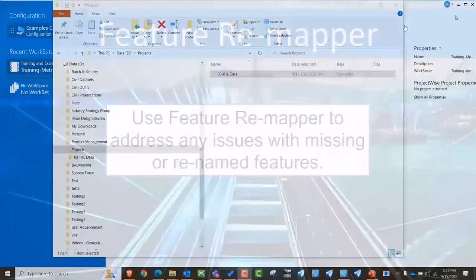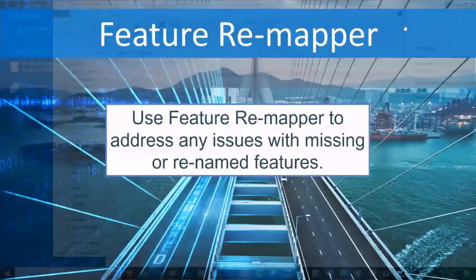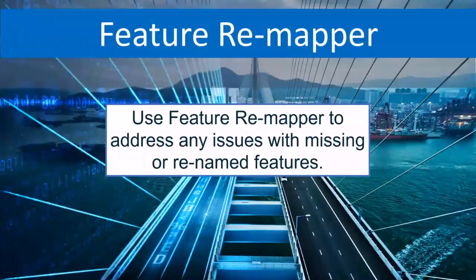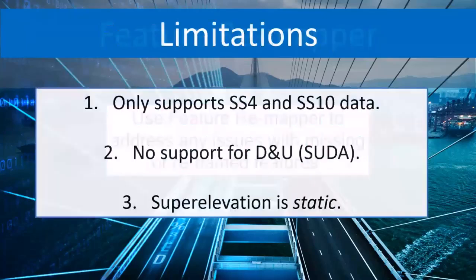Okay, now again, if after you've upgraded that data, you've got any issues with features, once again, just a reminder that this is where you would use feature remapper to address any of those issues with missing or renamed features. Now, a couple of limitations on the Civil File Manager.